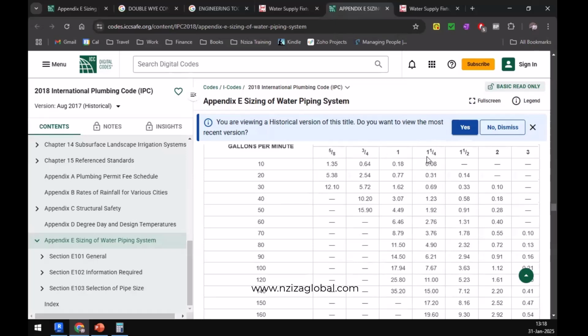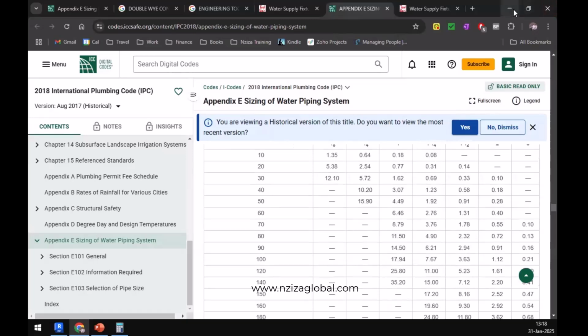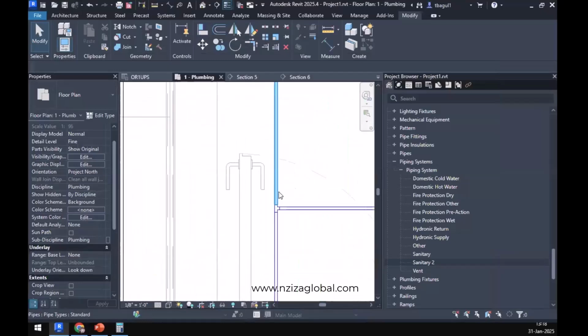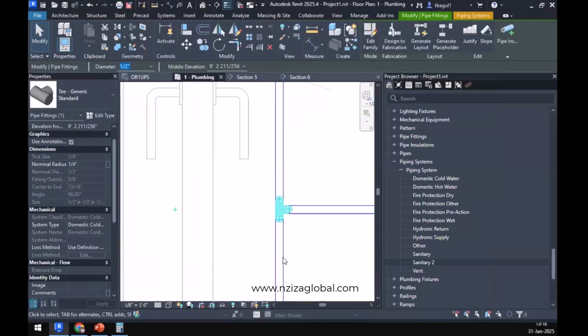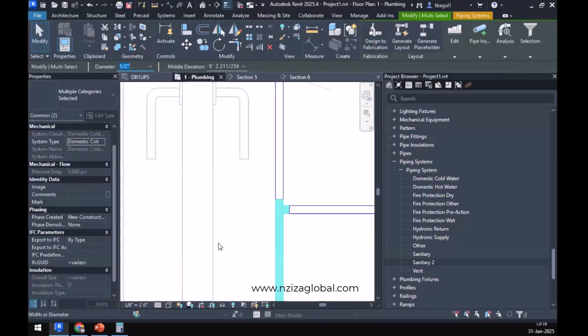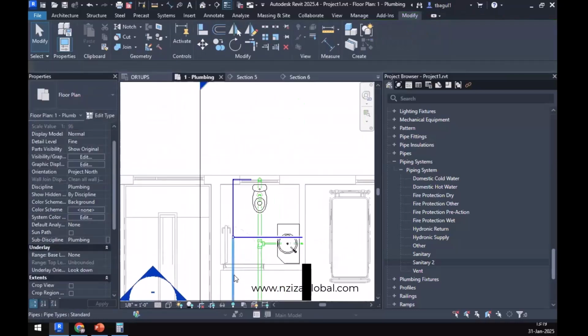All right. So if we are going to 0.1, we'll need to have a 1 1/4 inch upsize over there. So from a half inch, we are upsizing it to 1 1/4 over here. So over here, before it picks up, the size of the pipe requires to be 1 1/4. So anything after this will be 1 1/4. So a total of 6 DFUs are carried by this particular cold water line. Now it splits with 1.5 going over here, right? And the rest of the 5 DFUs going on this side.